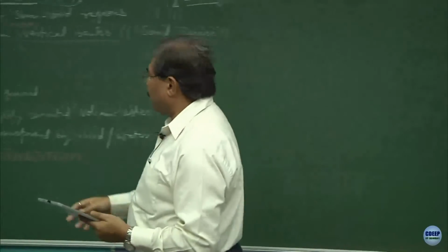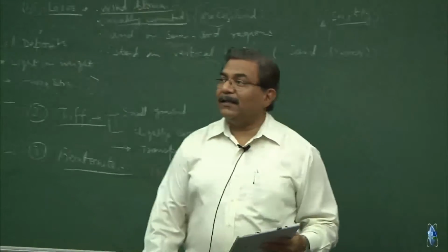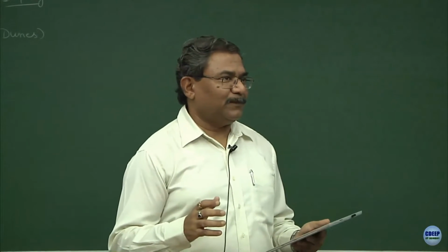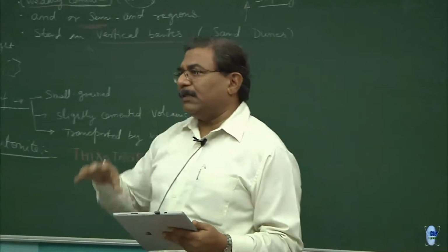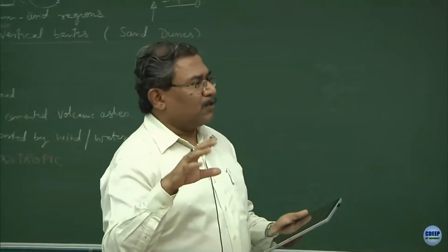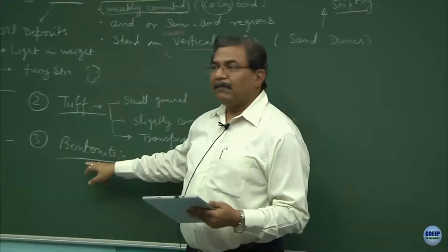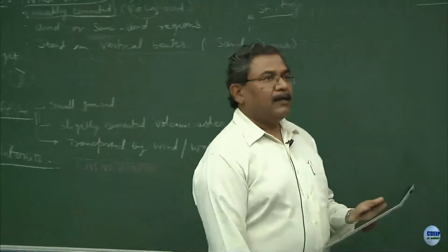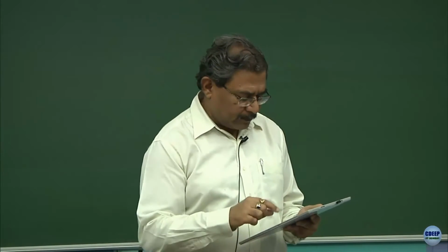So, these are the type of minerals which are very notorious, and in conventional subjects they have always been termed as unwanted materials, not bentonite, the montmorillonitic material. Those of you who come from Vidarbha region, central part of Maharashtra, MP, Karnataka, you must be seeing black cotton soil there. The constituent of the black cotton soil would be a cousin brother of bentonite, but by virtue of this material having thixotropic effect, this has become a boon in the nuclear industry, and we will discuss this if time permits.